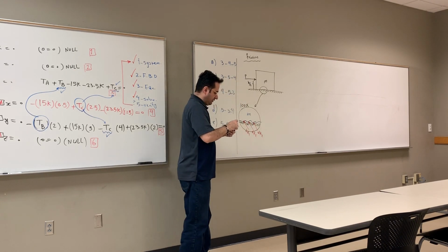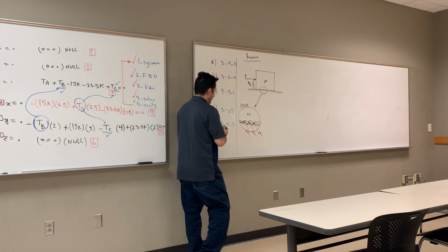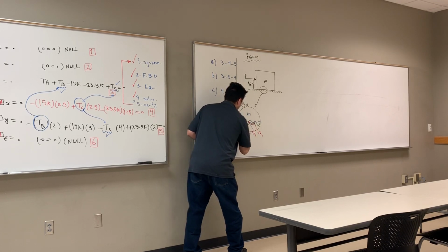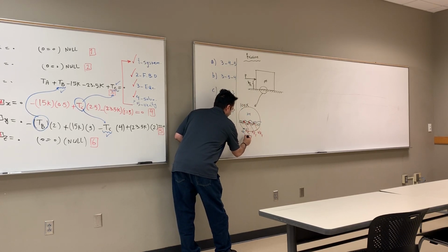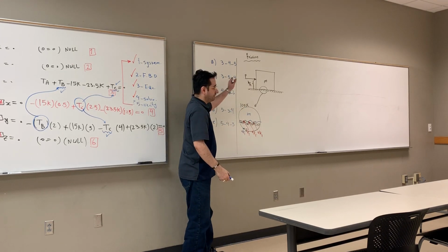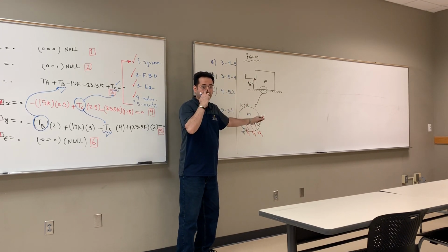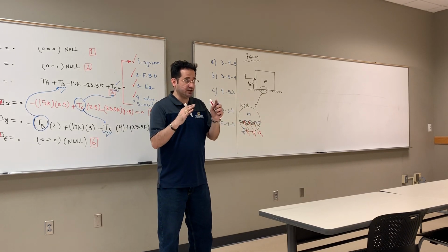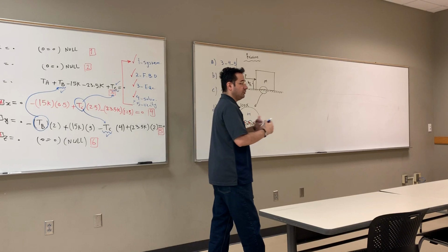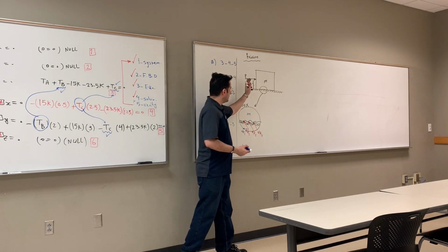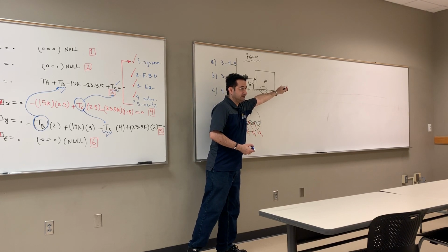So if I decompose each one of those, I get dF, the frictional force, which is opposite to the direction of motion. This is the point. The friction force is opposite to the possible direction of motion. It's not moving, it's about to move, but it's not moving. But the possible direction of motion is that way, right?